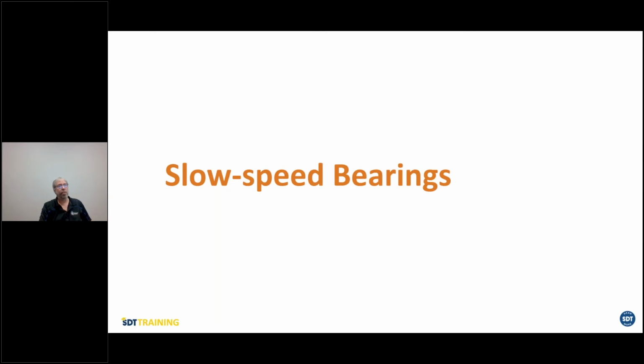It's the same for vibration. If you're turning very slowly, there's very little force, therefore the vibration doesn't necessarily pick it up. Whereas with ultrasound, we use the natural frequency of our sensor. The RS2T, I don't know if you remember seeing it, has this little tail on it. That gives the sensor a natural frequency of 40 kilohertz. So anything occurring at high frequency will automatically be amplified because our system is a tuned system.